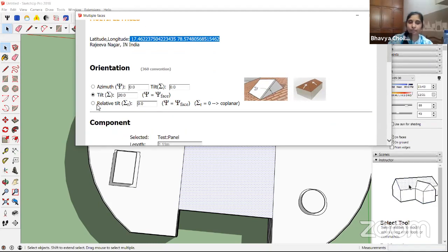Basically, the solar components will have some tilt angle based upon consideration. India is in the northern hemisphere, so we face our modules towards the south, and tilt angle is where you put modules at a certain tilt. The major reason is to trap the maximum irradiation from the respective locality, so you design a tilt angle consideration. I'm just giving you a brief about tilt.